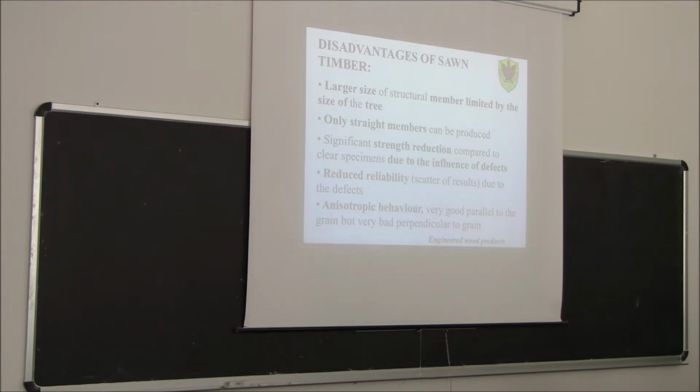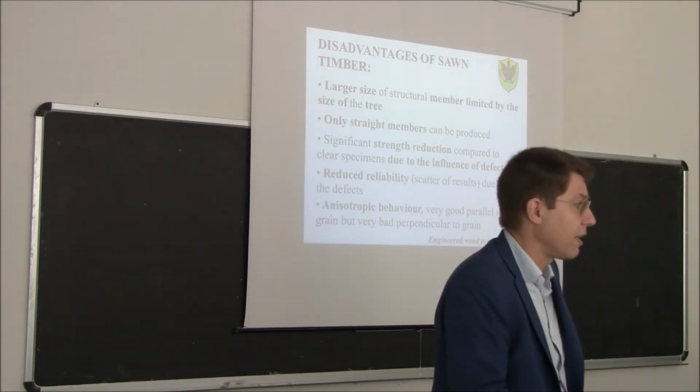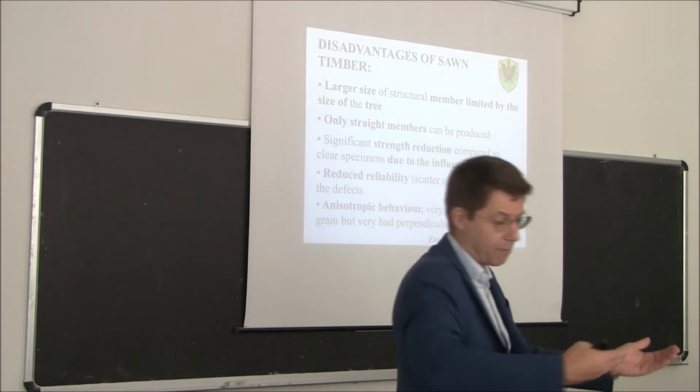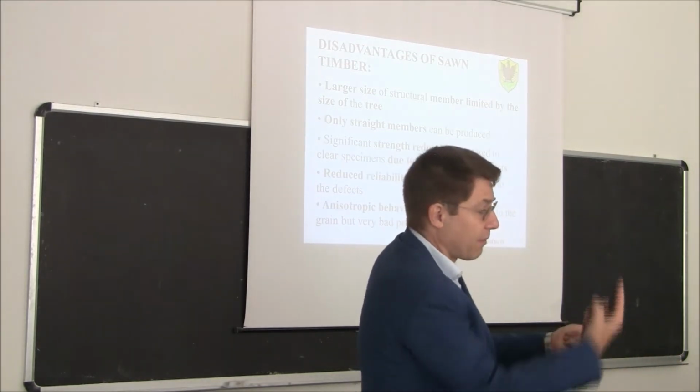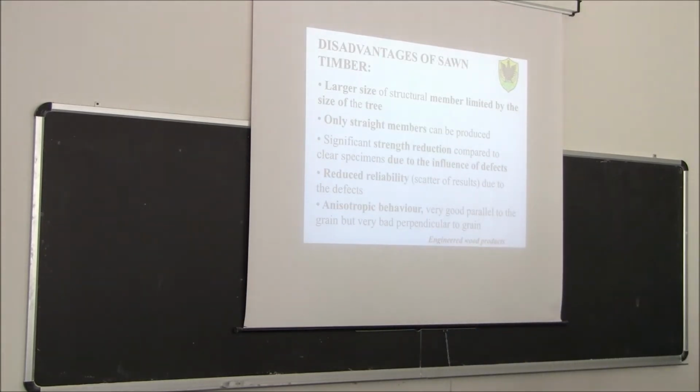For example, in the joint region, in a joint, you have some secondary stresses perpendicular to the grain. Usually we ignore those stresses when we design with concrete and with steel because the material is isotropic. So those are secondary stresses, lower than the primary one, but since the material performs exactly the same in the two directions, we don't care about that. Instead, for timber, unfortunately not. The secondary stresses may cause failure because they act in the low strength direction.